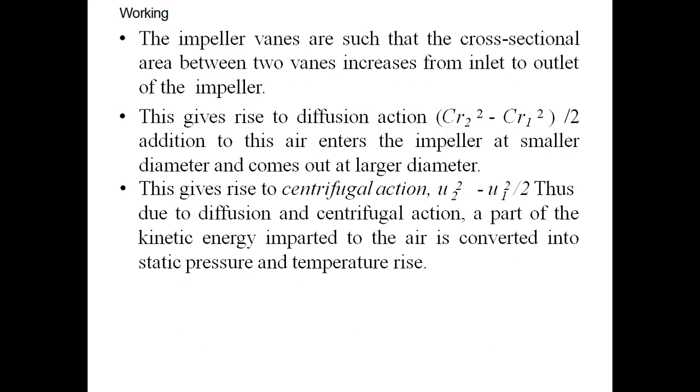This gives rise to centrifugal action, (U2 square by 2 minus U1 square by 2). Thus, due to diffusion and centrifugal action, a part of the kinetic energy imparted to the air is converted into static pressure and temperature rise.